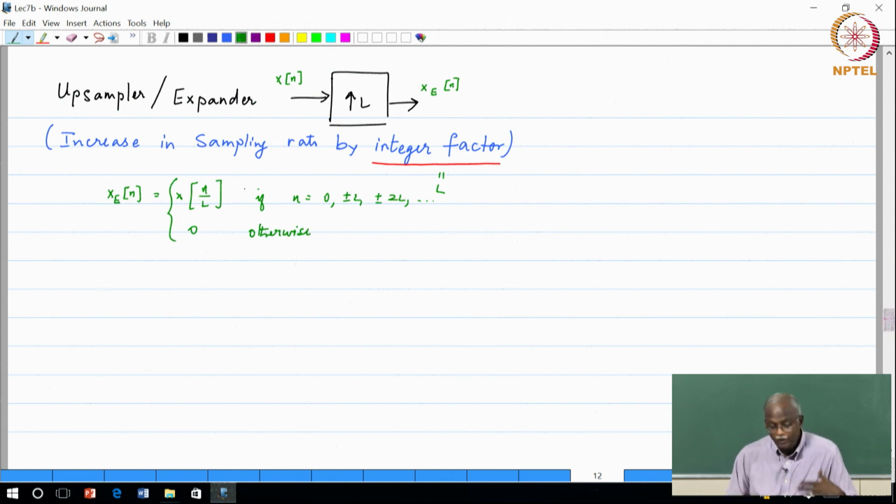Now, very important that I look at it in the frequency domain. So for the next few minutes we would like to obtain the frequency domain representation, and please follow along, because the notation and the expressions are very important for us. So we are trying to get the frequency domain or the Z transform. The Z transform, if I evaluate it on the unit circle, gives me the frequency response, the Fourier transform. So I will write it in terms of the Z transform.